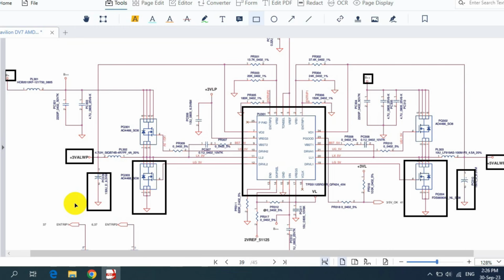When you find pins are bent, for example on a USB connector, HDMI connector, VGA connector, RJ45 connector, etc., you should always check whether the connectors are okay or not. Then a bad CMOS battery, or even the big battery, can cause a dead motherboard. That's why you should always remove the batteries.